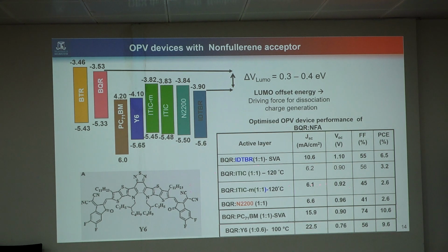I said material design is the first one. Next, choosing a good donor and acceptor with a good energy level offset, and also good mobility. The other thing is the good selection of your anode and cathode. In between, the interface is also very important, because everything happens in the organic, but charge extraction happens at the electrode, because the silver and ITO are inorganic.